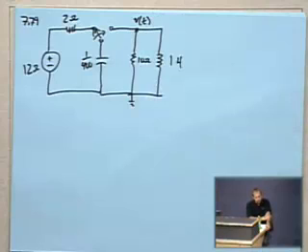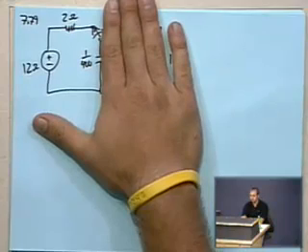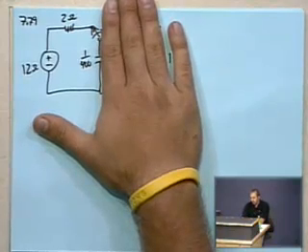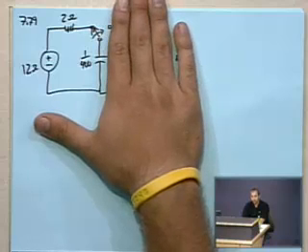The one thing that we talked about, at least briefly, was that for the first half of the problem, getting into the steady state and figuring out the initial conditions in this circuit, we do just a very mild amount of circuit analysis. Before this switch actuates, there is a voltage source, a resistor, and a capacitor. A capacitor acts as an open circuit during steady state DC conditions.